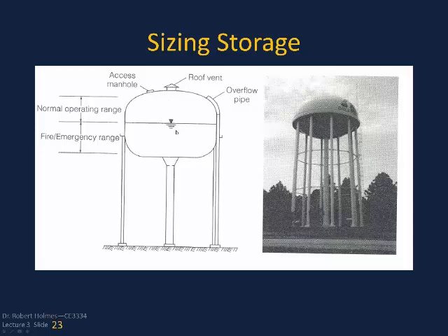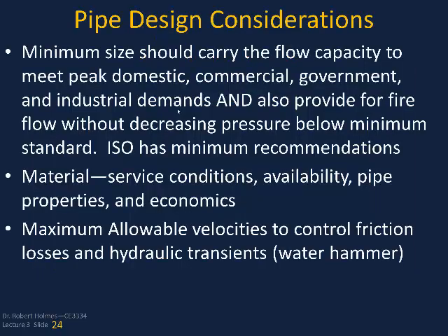So this would take care of it if you had power outages or leakage or a major bust somewhere. You get down into this emergency range of storage, or if you have a big fire, that's there for your storage. This is the area that you operate in for most of your water demand from your commercial, industrial, residential, government, and public buildings.